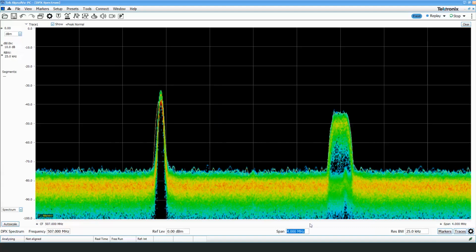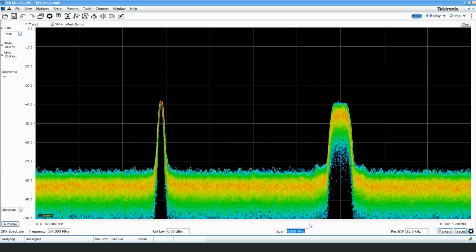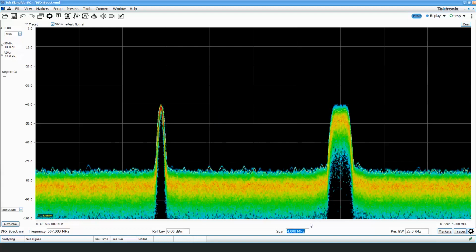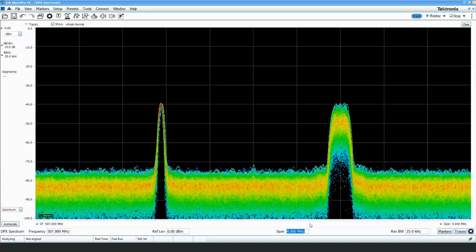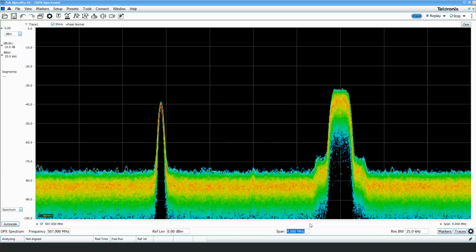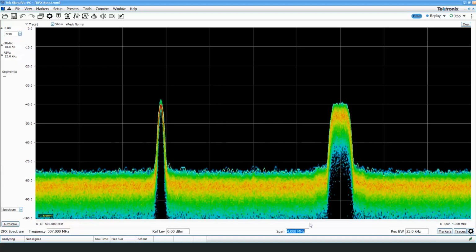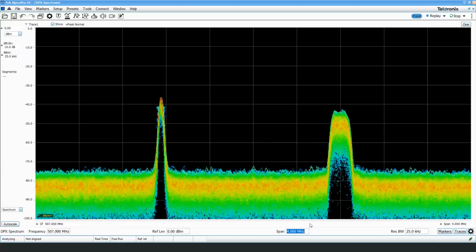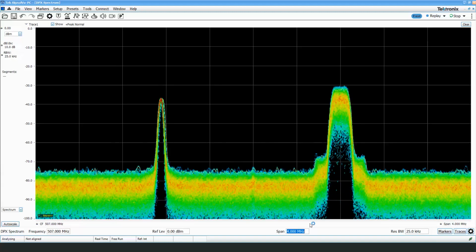An analog microphone uses frequency modulation. So any of these microphones for the FCC can take up 200 kilohertz of space in the spectrum and still be legal. So the analog microphone, we will vary its frequency a little bit, and we'll see this if I sing a tone into the microphone. We see the microphone modulate back and forth. A digital microphone, if I do the same thing, the one on the right,